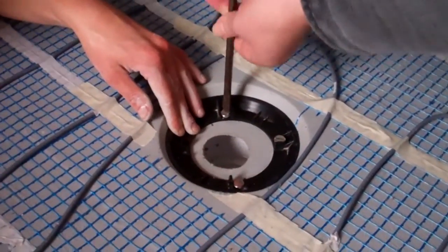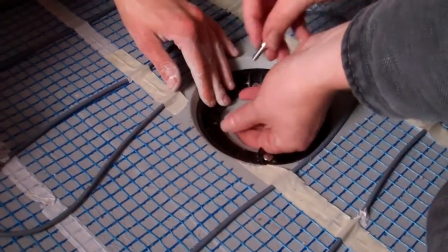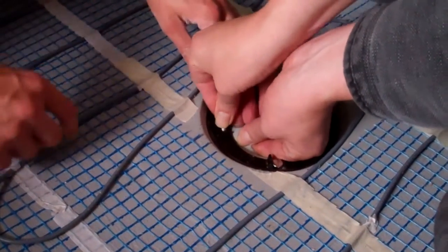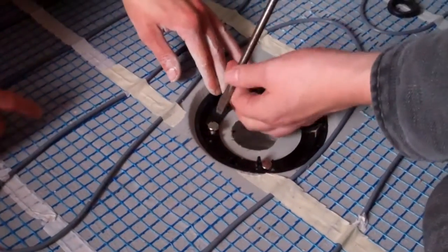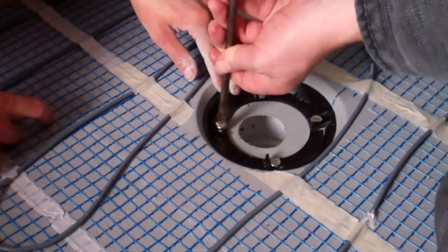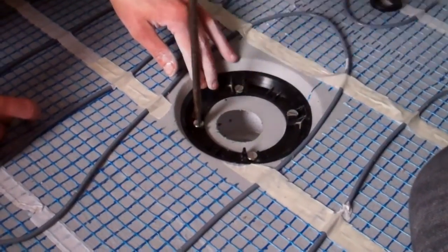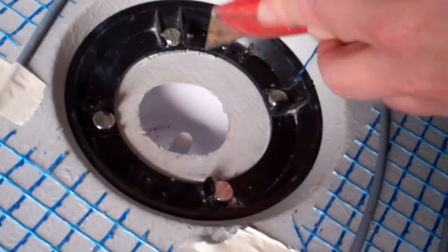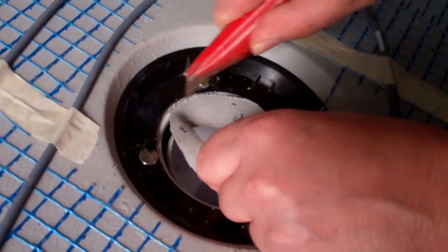An extra pair of hands is useful to hold the clamping ring in place. Pierce the large sleeve with a pointed tool in the 4 screw positions prior to inserting the screws. Only do this with the ring held down into its final position and don't allow the ring to move until all 4 screws are tightened into place. Trim off any excess sleeve showing at the inside edge of the clamping ring with a Stanley knife or similar.